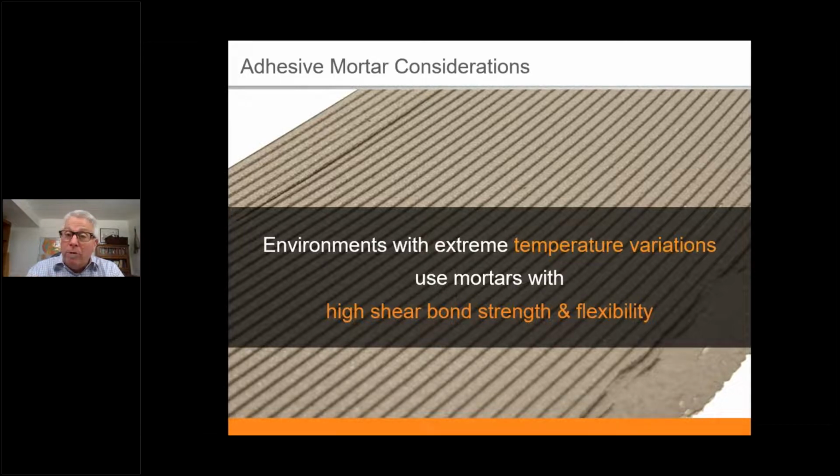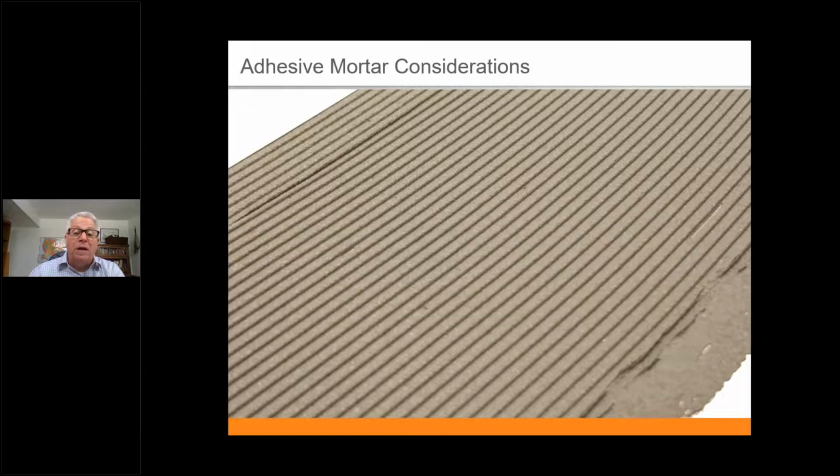It's not only for waterproofing and crack isolation, but it could also be in there to uncouple or isolate the tile from the dynamics that are occurring in the substrate below the tile, in the tile assembly below the actual finished veneer. So remember that all of these materials change dimension at a different rate and to a different degree depending on their material composition. And again, like I said earlier, how much heat, how much moisture they are going to be exposed to plays a great role in how much dimensional change those materials can have also.